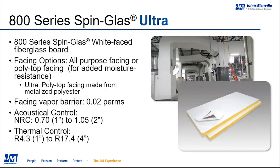800 Series Spin-Glas Ultra. Johns Manville's 800 Series Spin-Glas Ultra board is a new facing offering as of April 23, 2019, that is essentially paper-free. Faced 800 Series Spin-Glas board is designed for systems that operate below ambient temperatures where vapor barrier protection is absolutely required. 800 Series Spin-Glas board is ideal for applications in commercial and industrial heating, air conditioning, power, and process equipment. Some of the key features and benefits of this product include the vapor barrier of 0.02 perms.